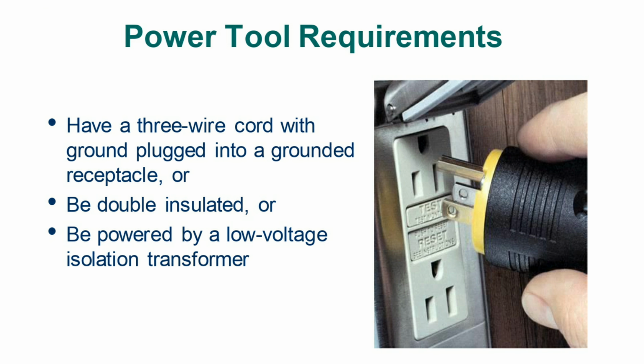Power tool requirements: have a 3-wire cord with ground plugged into a grounded receptacle, or be double insulated, or be powered by a low voltage isolation transformer.